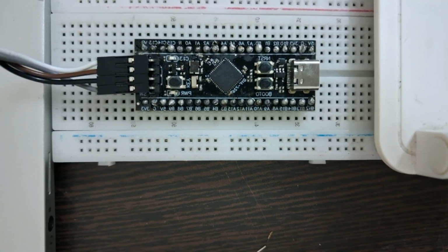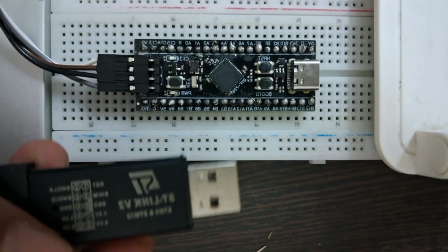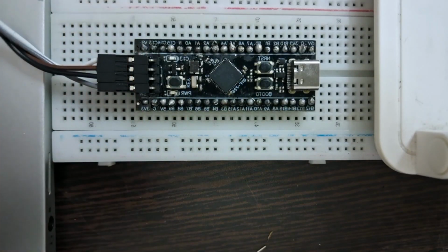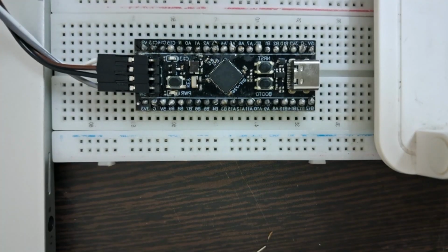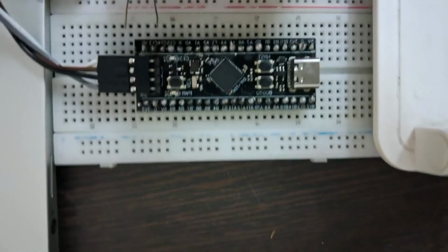Here is the shot of a microcontroller. It is connected to this ST-Link V2 programmer that you can get online. Here's the top shot of the microcontroller, and this is a LED called C13. It is called the LED C13 because it is connected to the pin C13. This pin is also available as an output for us. So we can connect an individual LED as well as the onboard LED. Both are connected to this pin C13. So let me just connect this external LED to this pin C13.